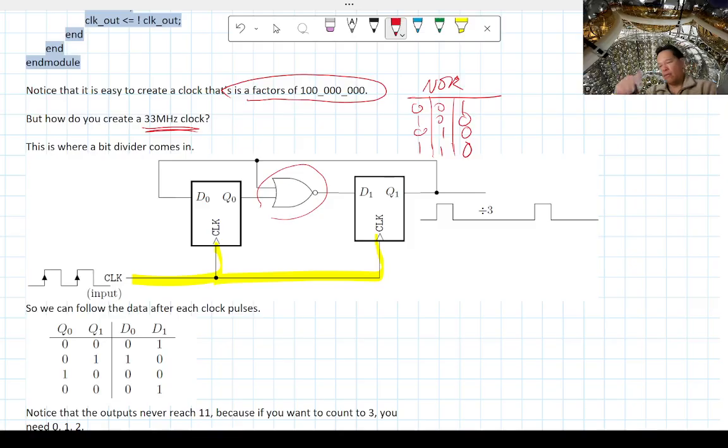Okay, sorry. So let's just read it from top to bottom. It's 1, 0, 0, 0, 0. Okay, so the only time that the output is high is when both inputs are 0, right? Because that's when the OR gate is 0, but you take the complement of that. Okay. All right, so let's see how this circuit works.